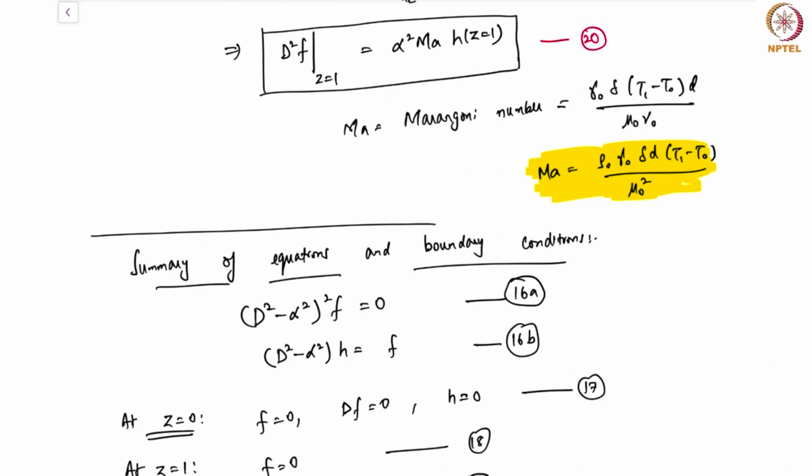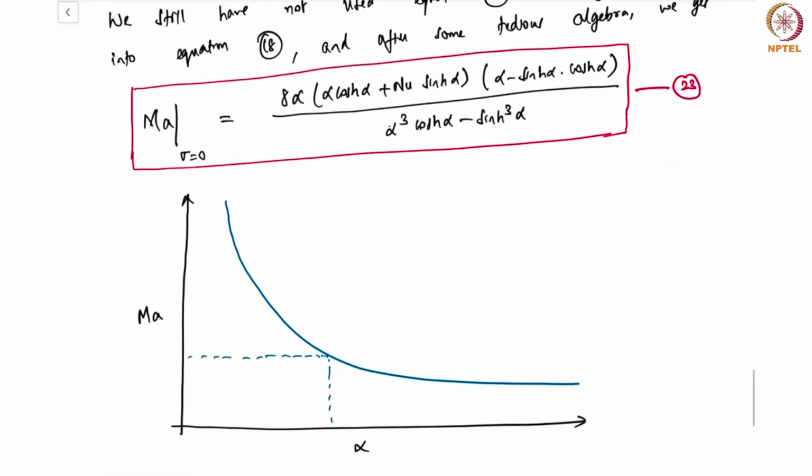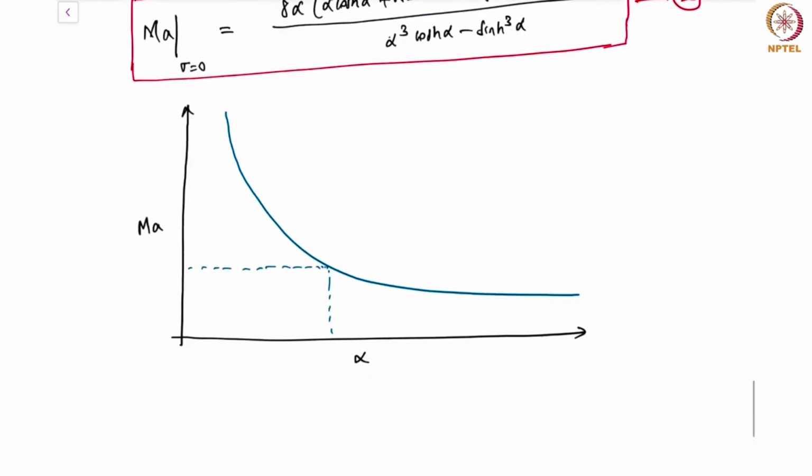Small temperature variations are enough to create appreciable changes in the surface tension value. And these changes in surface tension create Marangoni stresses at the interface and drive a convection. It drives an instability. So if you are below such a curve, then you are in the stable region, and if you are above such a curve, you are in the unstable region.